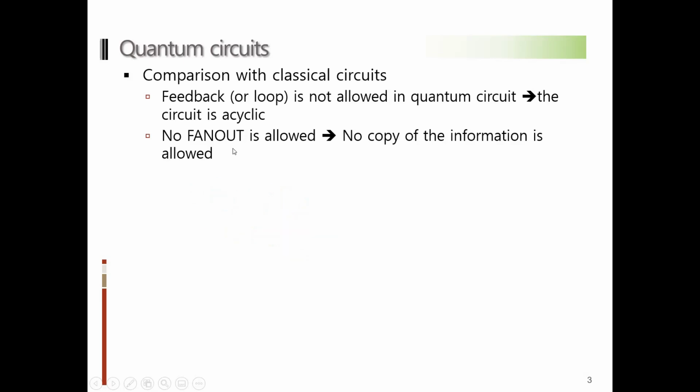And also, the opposite, fan in, is not allowed. Fan in is the opposite concept. In some circuits, you can actually directly combine these three wires together, and depending on the type of the gate connected to the next one, even this kind of connection is allowed. In typical cases, this is used to implement an effective OR gate. And this kind of situation is called fan-in.